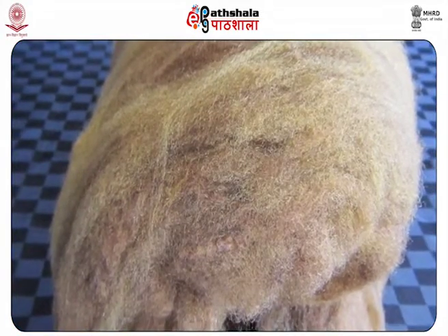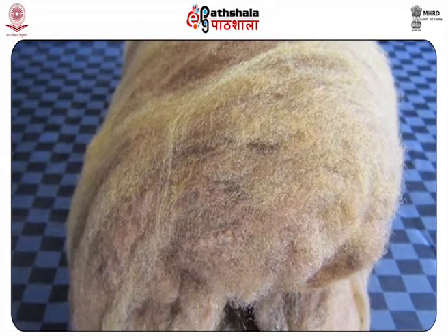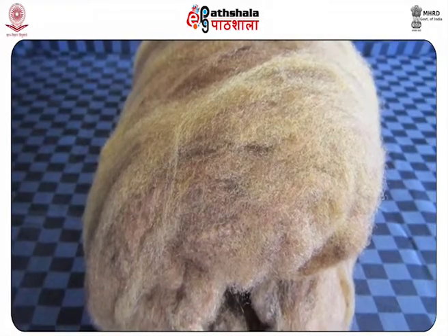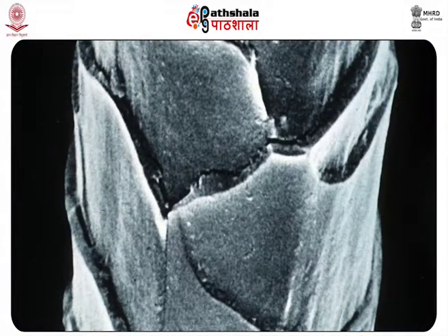Not all animal hairs have the same properties, and even within a species the fiber is not consistent. Merino is a very soft fine wool, while cast wool is coarse, and yet both merino and cast wool are types of sheep. This comparison can be continued on the microscopic level, comparing the diameter and the structure of the hair. With animal fibers and the natural fibers in general, the individual fibers look different, whereas all synthetic fibers look the same. This provides an easy way to differentiate between natural and synthetic fibers under a microscope.